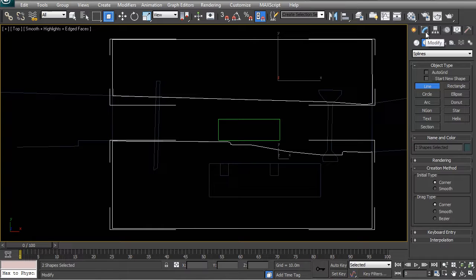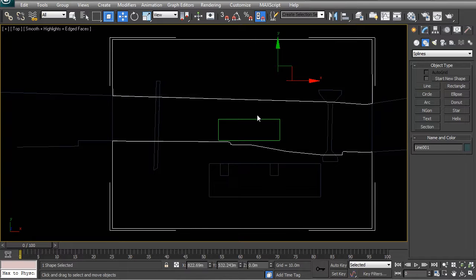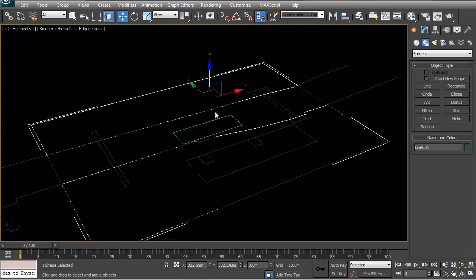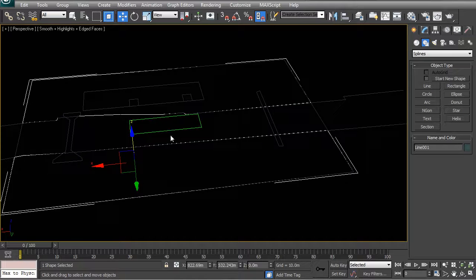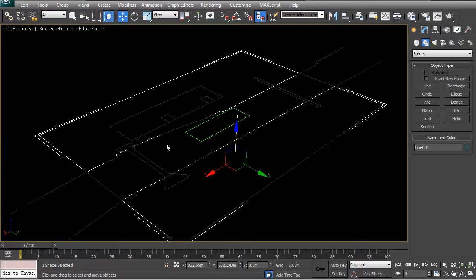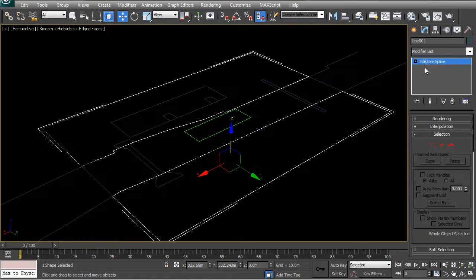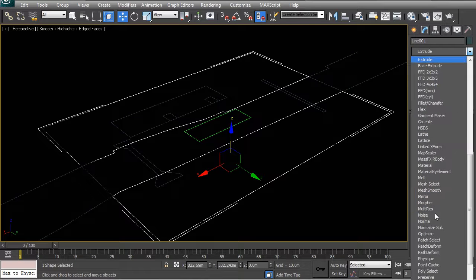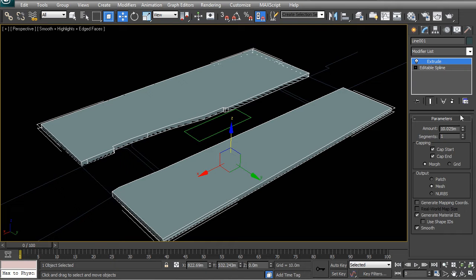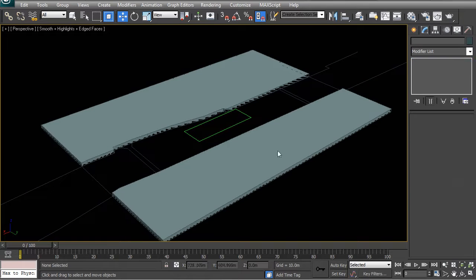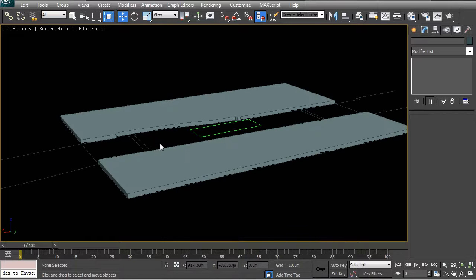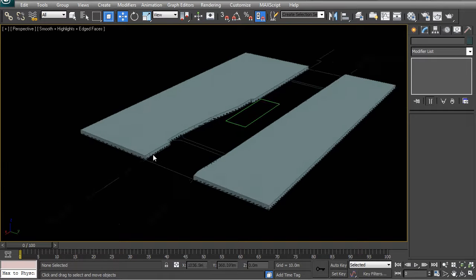It's much easier to have a very simple and low amount of base objects and then to work on them as one. So I'm going to be repeating that idea as we go along through this course so that you can see. So immediately now I can go and extrude this upwards. So type in EXT, enter, and I can extrude it up by, let's say, 8 meters. And that 8 meters has been taken as an eyeball figure by looking at my reference photos from the site.